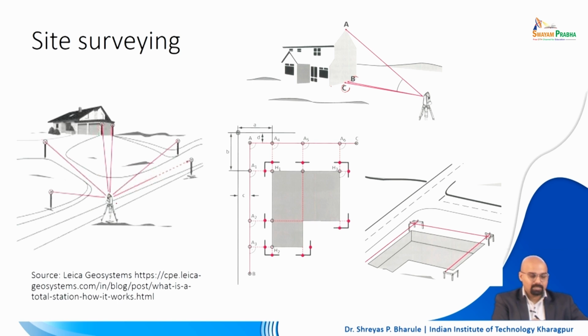Now, coming to another example which is here. What is happening in this case is, say for example, you definitely know that this particular building is not going to move. So, 2 points become your reference for identifying the location of the total station, right. Next, you use 2 junctions, which are the edge of the road on either side and the edge of the footpath on either side, to get another reference, right. So, it is double, triple, 4 times or 6 times; probably it has 6 references. It has been checked 6 times to identify this one particular location, right.